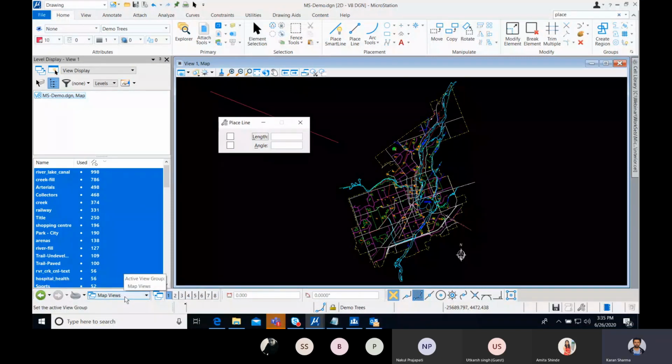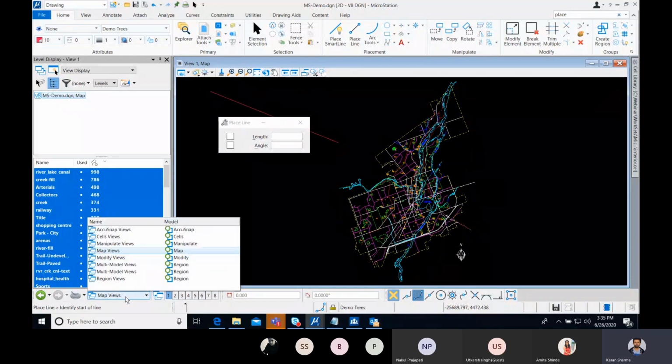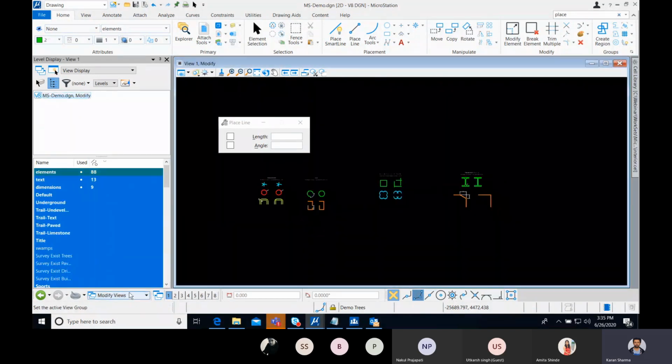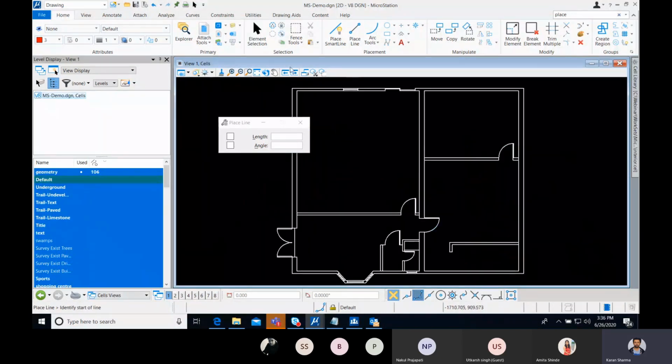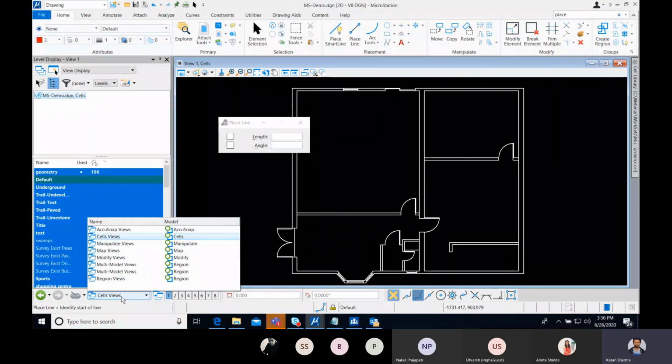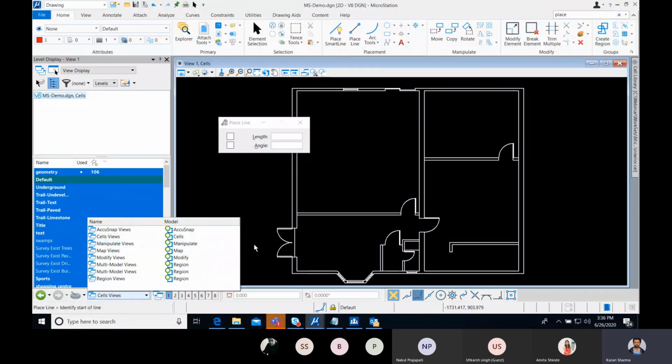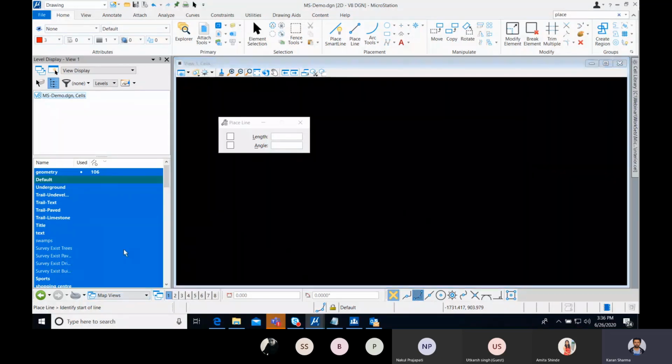Then here is a cool feature specifically in MicroStation. We can have multiple models within a single DGN. Just like here, you can see I have multiple models which I have created to demonstrate various features today. So from within one file, you can have multiple models, and they are independent of each other. They can have different units. They can be either 2D or 3D. So they're not dependent on each other. Just like Excel, you can assume you have workbooks and within them you create sheets, right? So it's kind of that. It's a nice feature.